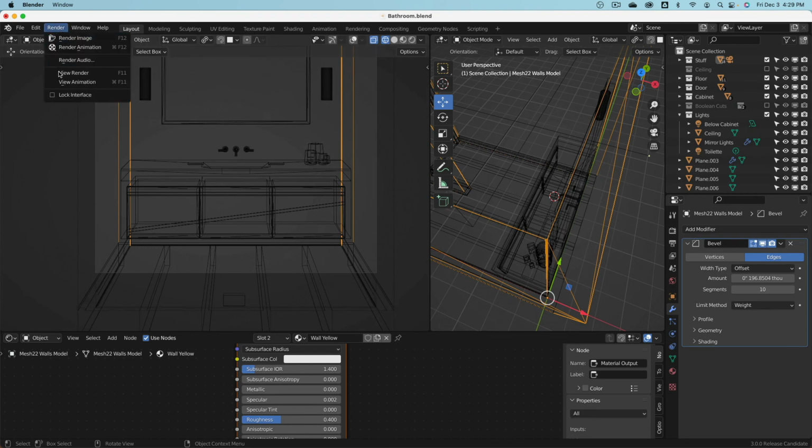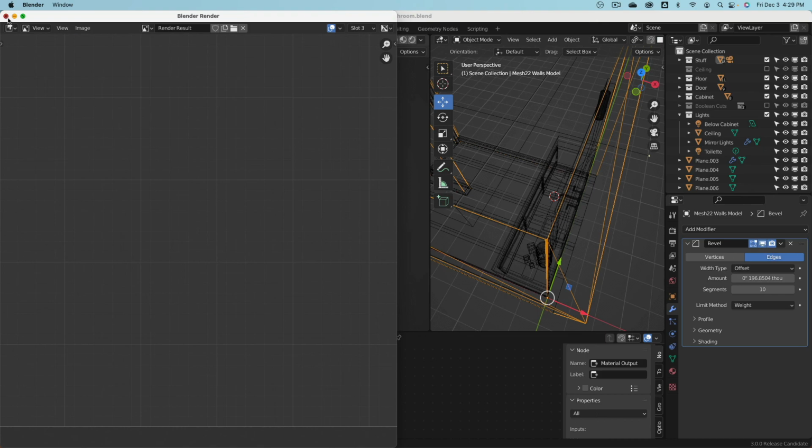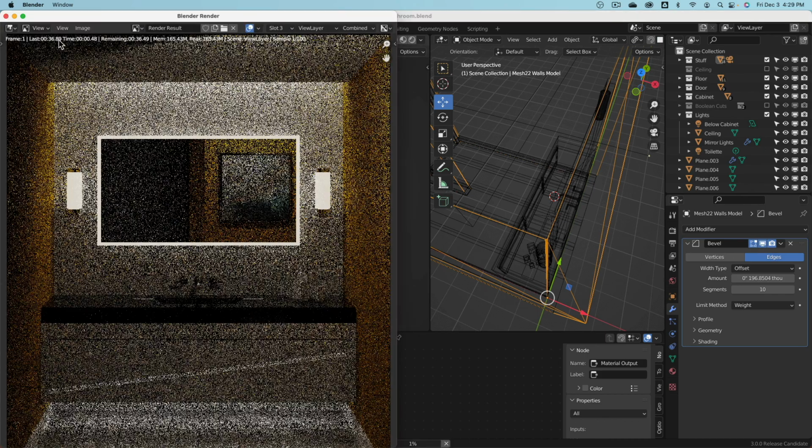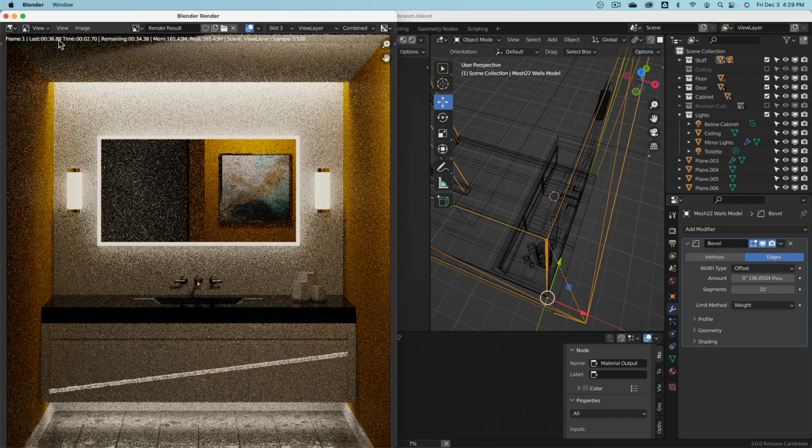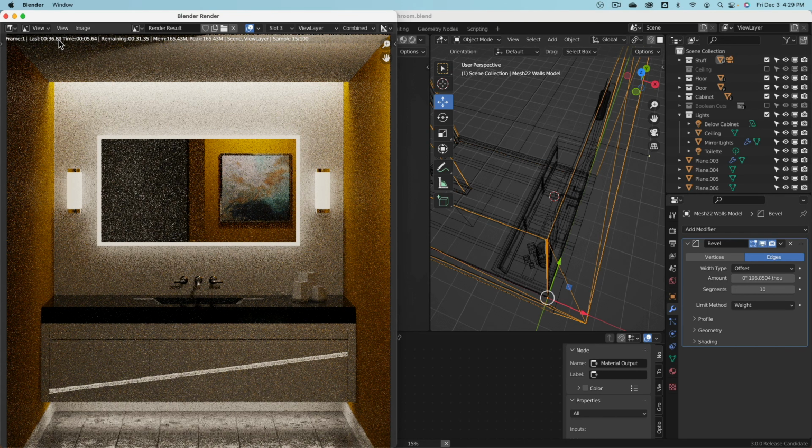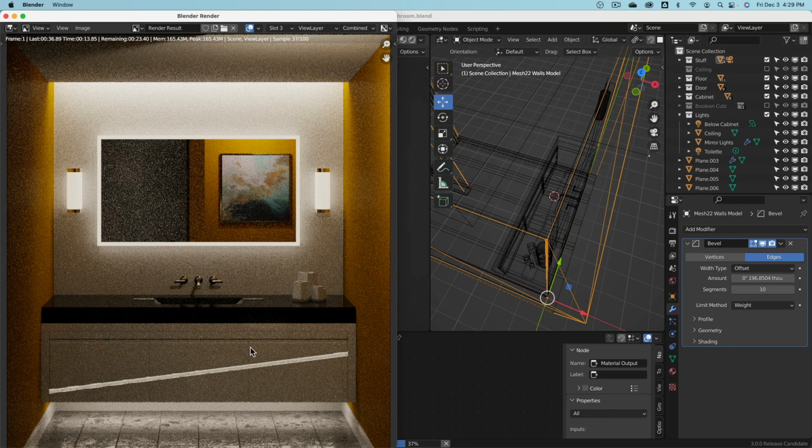So view render, very good. In this slot 3, we would like to render another piece. And you see, because we give this more samples, it has more time to also calculate these fine details, which is still way too tight. But instead of modeling the doors a little bit smaller, where they should be, I artificially round the edges when the edges are rounded anyway. But this way, I'm creating this visual cue that there is something happening.